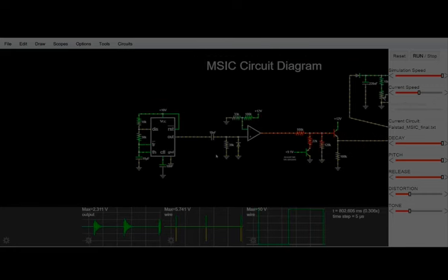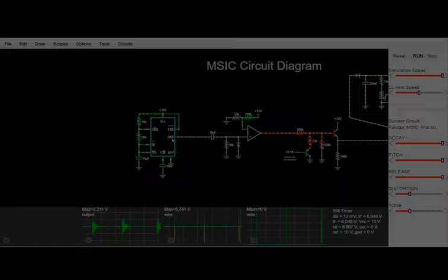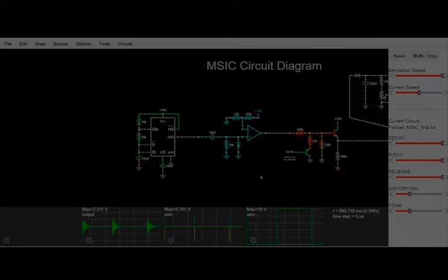Now, if we directly feed these long gate signals into the kick drum circuit, we get two kick hits, one when the gate goes high and the other when it goes low. So we need another circuit to solve this. So here we go. This is that block.